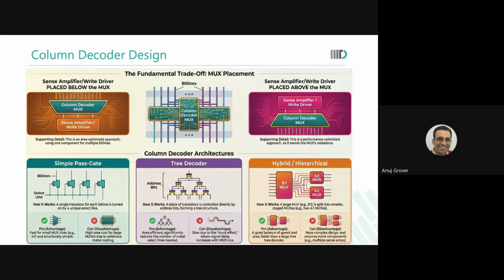The bit lines can discharge into leakage, and that can cause corruption of data, because the one stored inside one of the cells, and there's the bit line and it is discharged, so it can actually leak through the pass gate and change the data inside the cell. It will weaken the stability of that one because the PMOS is already the weakest device in the memory cell, and it can result in a data loss. The retention voltage can suffer.